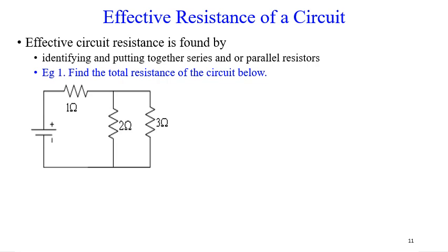So let me now consider another set of resistors. Are 2 and 3 in parallel? Then let's use our circling method. I move from here to here and back here. I realized that I didn't meet any third element. So meaning the 2 and 3 are in parallel.